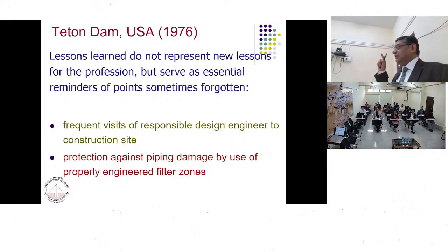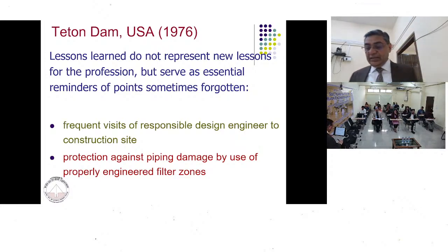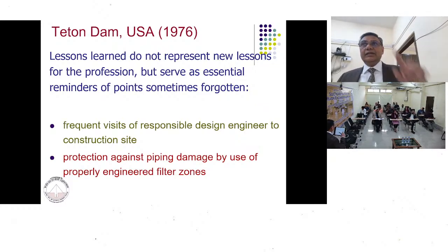One more thing which occurred here, in this particular case, was that the filter was not correctly designed. The filter was not able to secure the silty material within the section of the dam, and that is why this piping started.